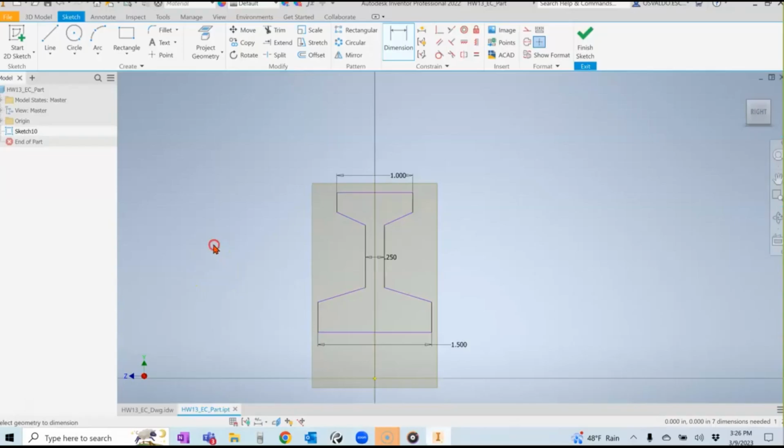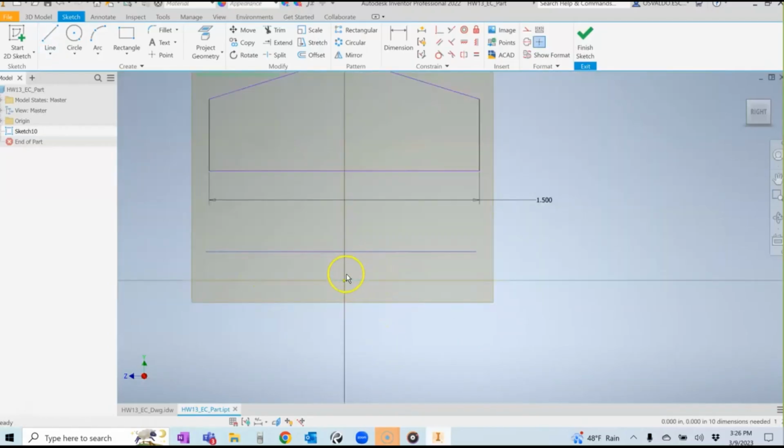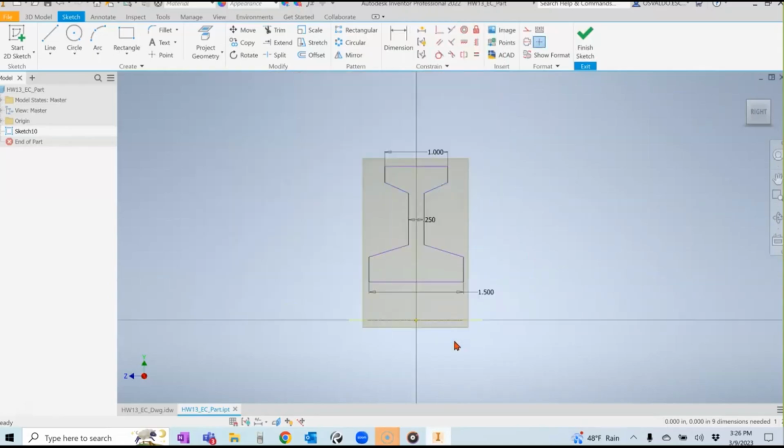So actually, this is the point that it would be a good idea to create a line. Okay, this line that is there. I need to lock it to the plane because that one will allow me to create like diameter instead of trying to go and divide every dimension by 2. So I'm gonna align this guy to the plane, and I'm going to change the line type to a center line. Center line. Everybody got what I've done?